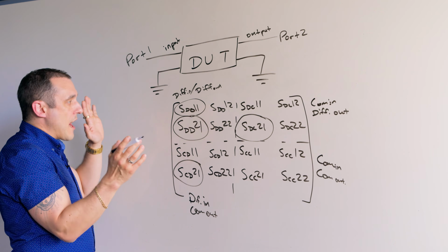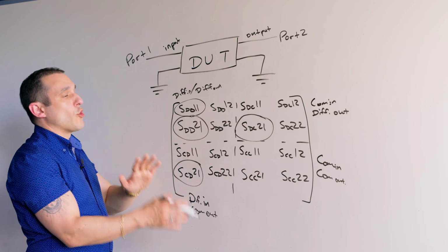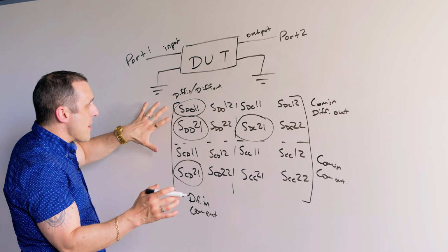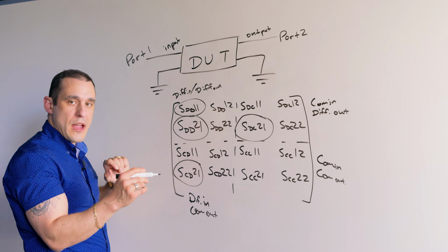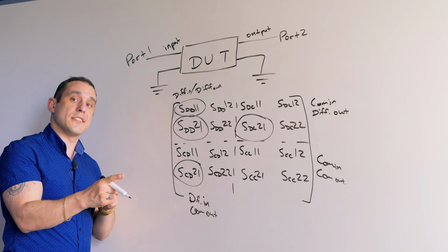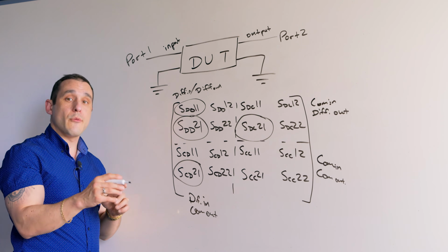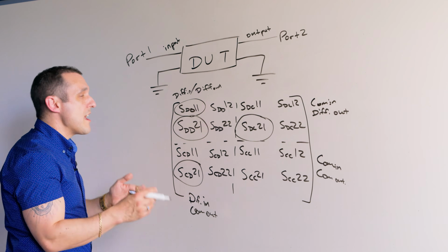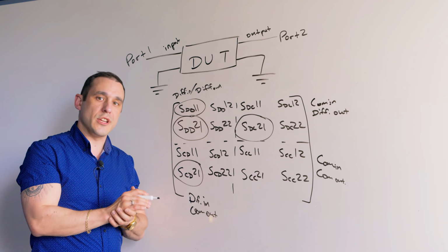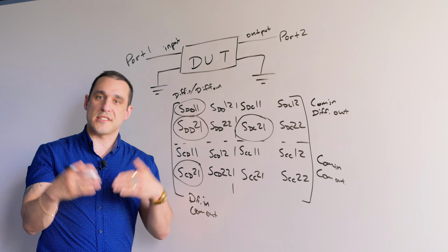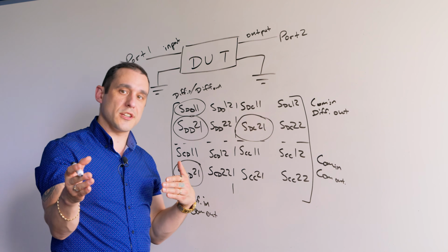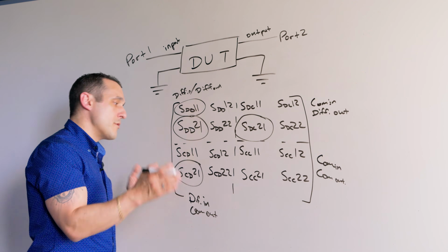So now that we've defined what exactly we need to look at to qualify a channel, which is primarily these three S parameters, we can go ahead and look in Simbeor at an example board, and we can do a quick simulation to qualify just how much length tuning is going to be too much and to what extent or what frequency range we really start to see an effect on mode conversion.